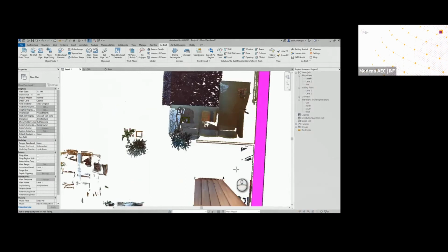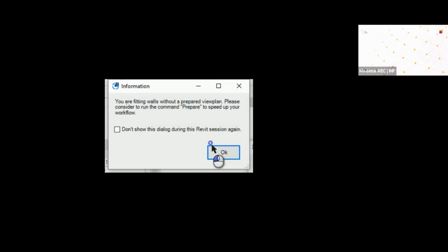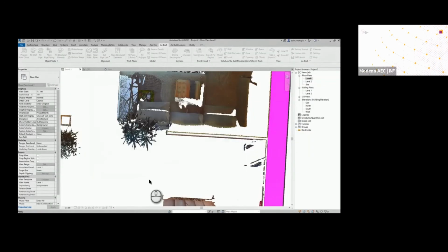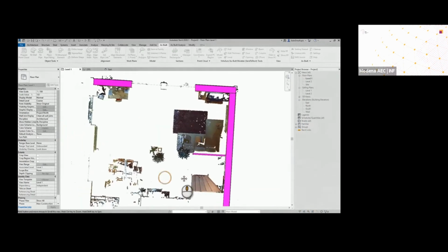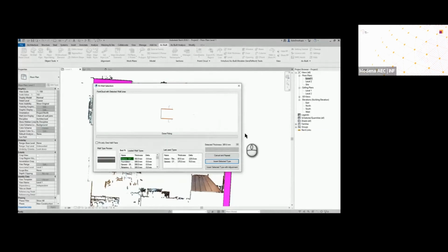Please note that this happens for any type of wall size. For example, I've got a smaller wall right here. The idea is I select point to point, allow for Revit to register those points, and again, insert that type. There is no actual need for me as a Revit designer to now go to my architectural walls or my structural elements and create the wall type myself, when AsBuild for Revit can do it for me at any wall size, at any shape size for the wall.